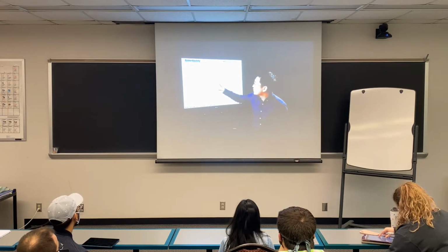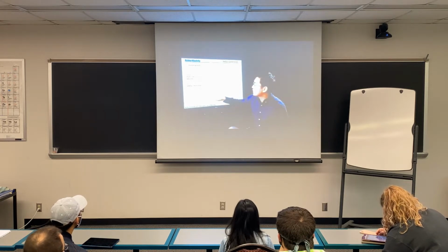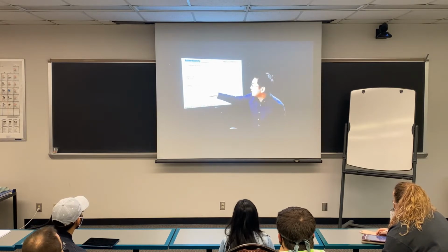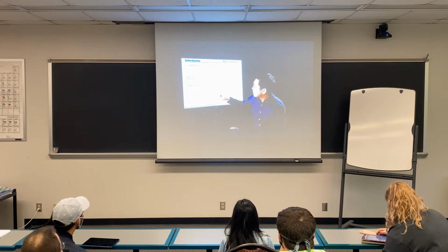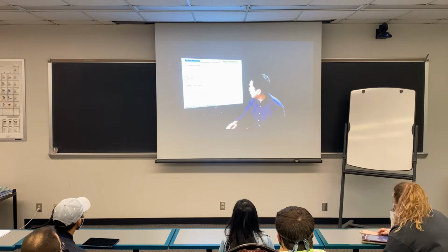Chain conformation under strain follows a Gaussian distribution. As I mentioned, this is one of the big reasons we need to address this. And this was done by adding an inverse Langevin function. This was done by Jung. So this approach is slightly different, where people added an additional term to account for non-Gaussian behavior. Okay?